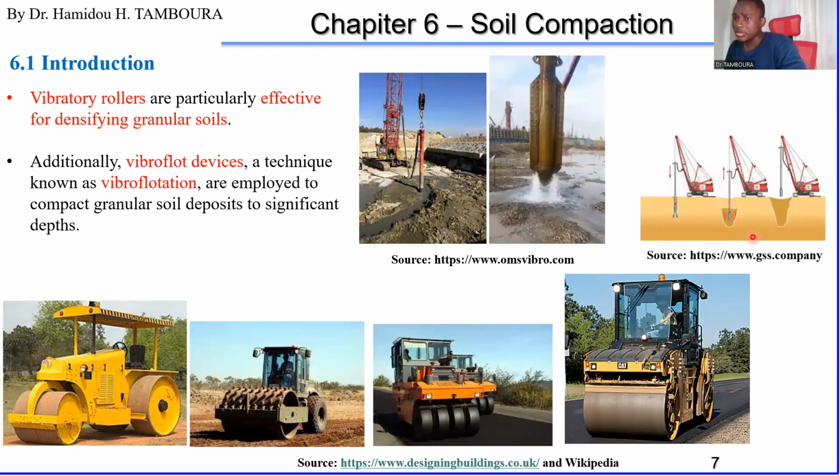This is the explanation of the technique. Just insert, you see the arrow here. Maybe it's small, but just insert this device in the ground like this and densify. After bringing vibration, it will densify the soil. And you pull out your device, and after that, this part of soil will be densified. So this is how we do compaction, because compaction is just densification, okay?